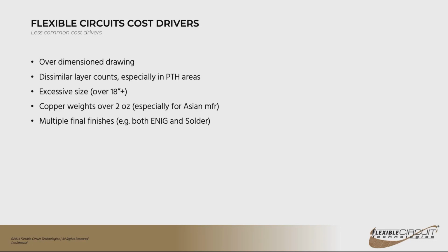One thing that I would caution you on, there's two different types of ZIF connectors out there. There's a single row, which has been in use for about 30 years and is very reliable and tried and true. There's also a dual row ZIF option, and those have been problematic for the industry in general. If you're doing something that's small quantity and you have very skilled operators doing the installation, you shouldn't have a problem.